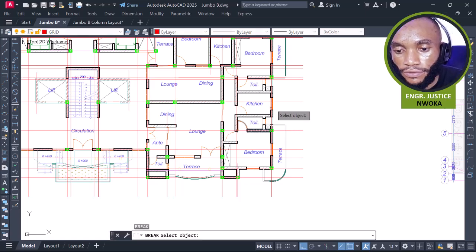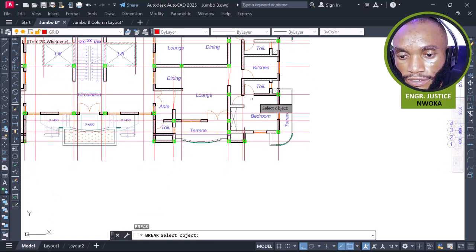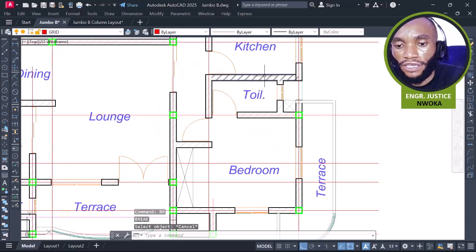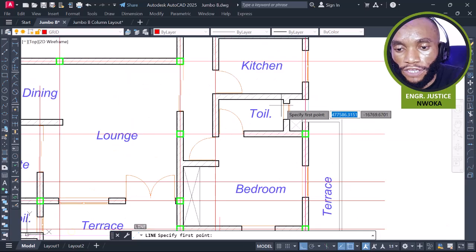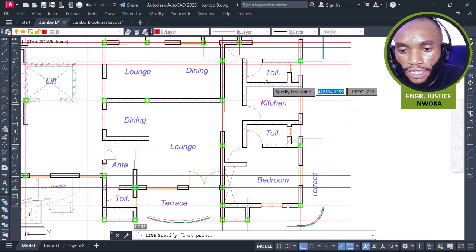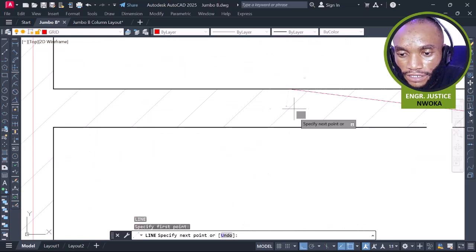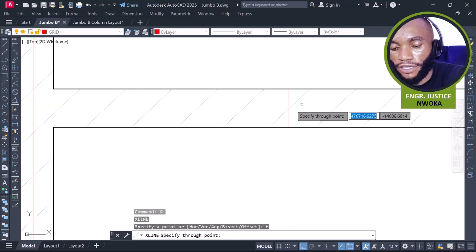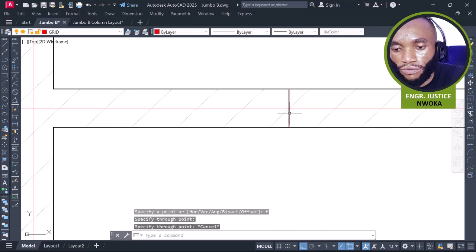BR. That's okay. Now we need to also establish a grid line here, at this lab kitchen wall. Let me see. Okay, no, this place here needs a grid line. Yes, here, and then XL, enter, H, enter, place at the center of the wall.